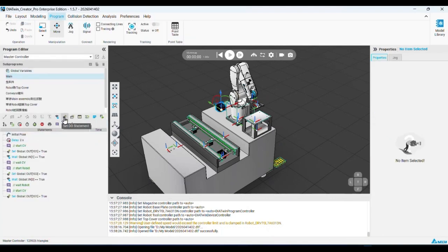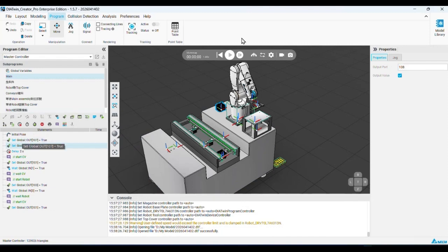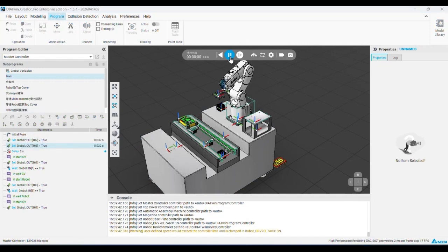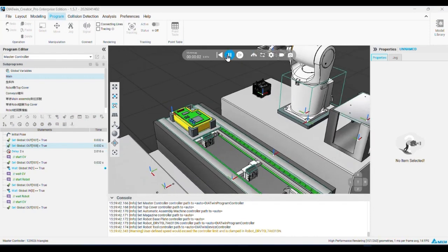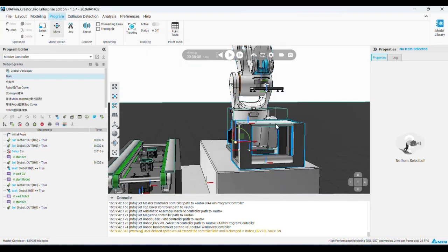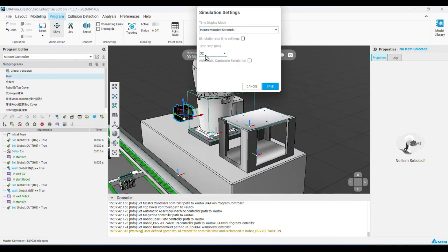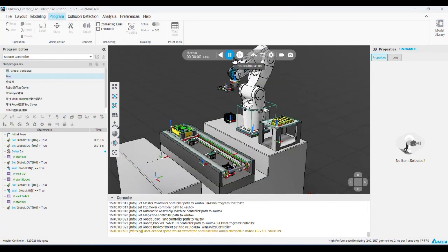I will start 107 and 108 to generate these two products. When we start the simulation, you can see the assembly now generates properly. But the top cover just penetrates because the plate is too thin. So maybe you can enhance the precision right here. It's safe. Now we can try again. Yeah, you can see you now have a better result.